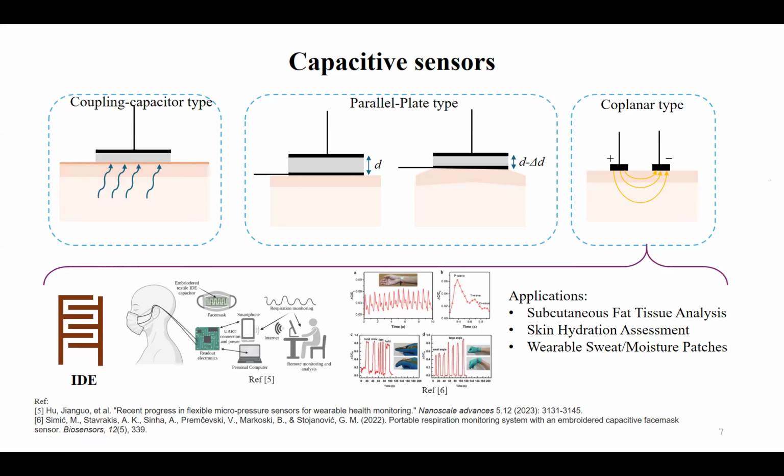So we can design a capacitive sensor easily by simply designing its area and the distance between the plates. It's very straightforward to design the sensor appropriately for any application. The only thing that we need to check is what should be its sensitivity and what should be its resolution. Based on that, we have to carefully design the area, even its type in which we need to align, that is parallel or coplanar and so on, right? So this is the capacitive sensor.